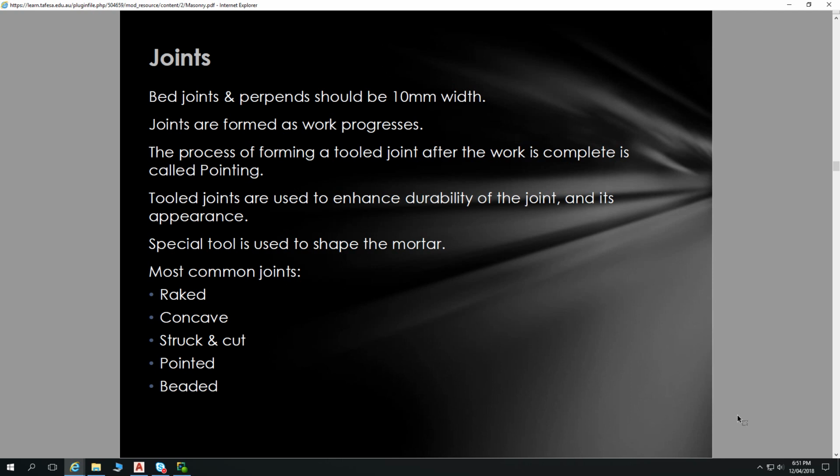The trowel is what we use for actually getting the mortar in place, typically when we're doing stone work. Pointing is about neatening up all the joints in the brickwork. The pointing tool with the handle on it is for doing a concave joint. And the square one is for doing your various other sharp shapes, so your rake, stroke and cut. That's called pointing.